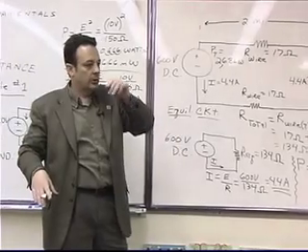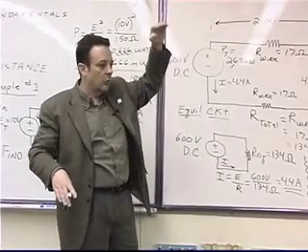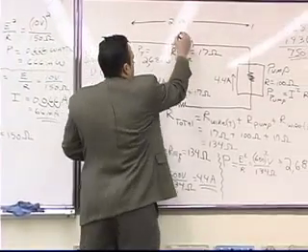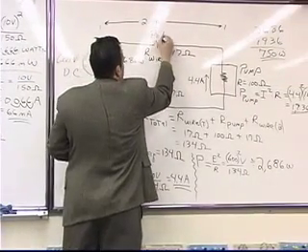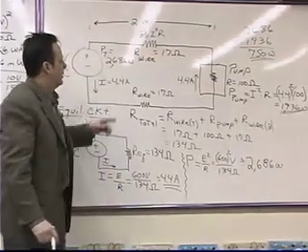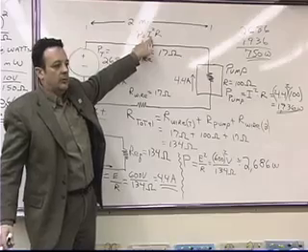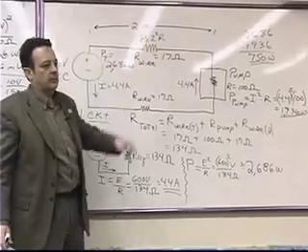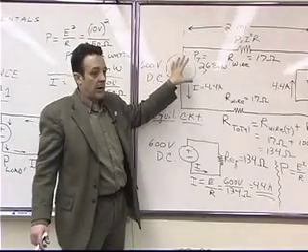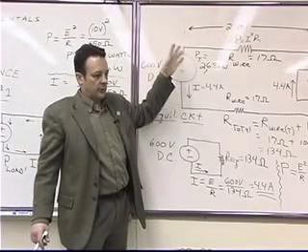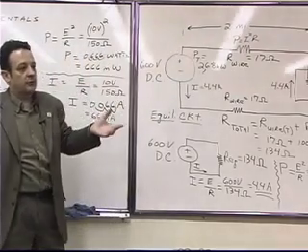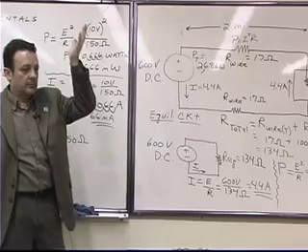So if the voltage goes way up, the current goes way down, and then the power, which is equal to I squared R, that's the power lost in that resistor, goes way down because the current goes way down. So one way to rectify this would be to go out and buy an inverter, convert this to AC, and then put a transformer to step the voltage way up.